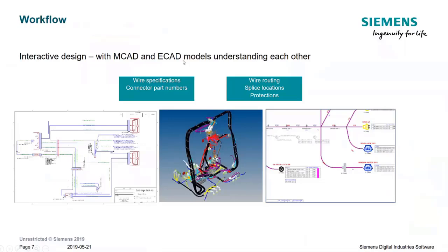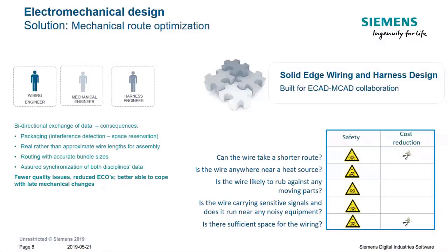I would point out some differences in the life cycle. First of all, connector part numbers. What's the advantage of having the connector part numbers for the assembly identified early in the process, at the time you're doing wiring diagrams, before you fully physicalize it into a harness interconnect? That gives a tremendous advantage in previewing the logistics for manufacturing, and potentially it can reduce the burden, the cost of freight, because of long lead times for connectors and the difficulty of obtaining them for manufacturing at short notice.